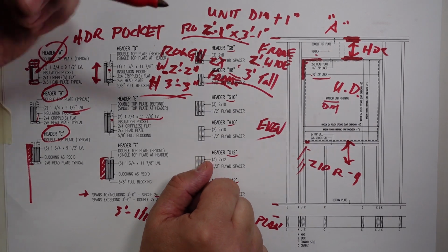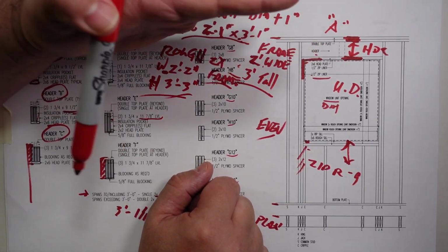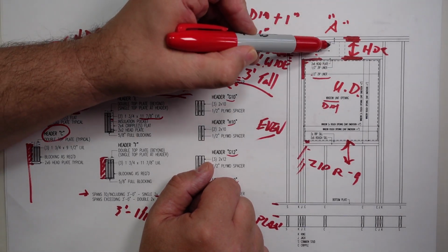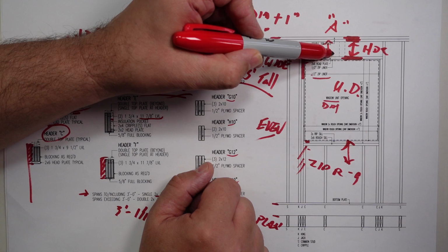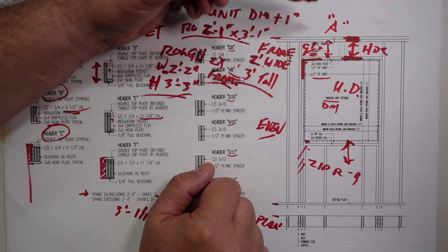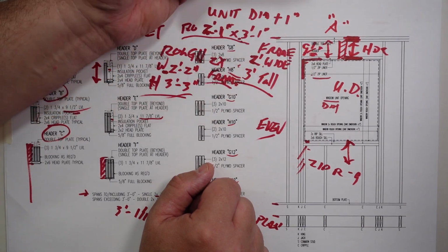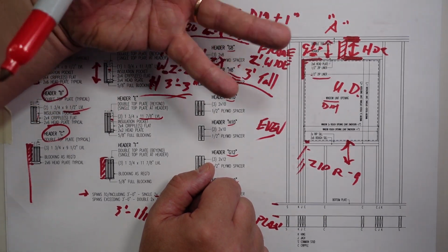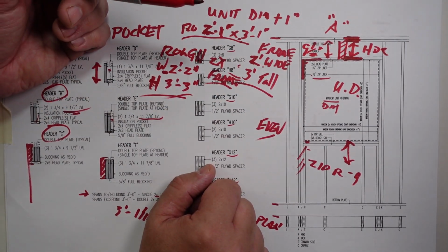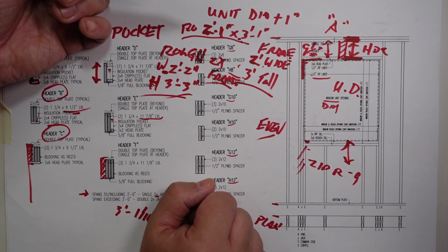A lot of times builders want to reinforce and keep that 2x from maybe going a little wonky or give some drywall attachment, even though this is only 9.5 inches. So it clearly makes the span for drywall, but we'll put a 2x4 on the flat there in front of the header pocket that we can insulate around and behind, but then that gives us some attachment for trim and all of that good stuff also on the inside.